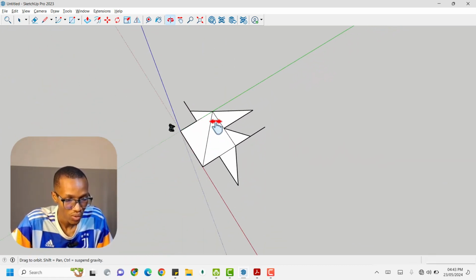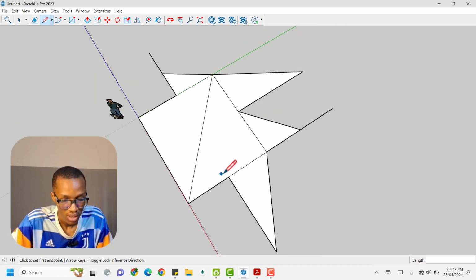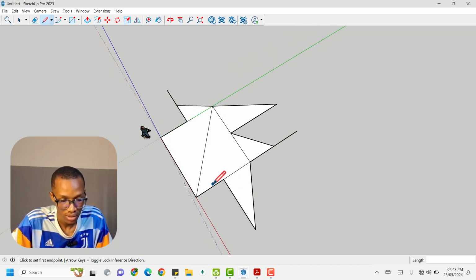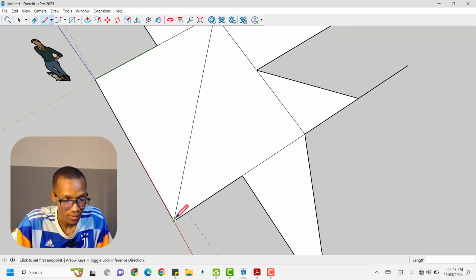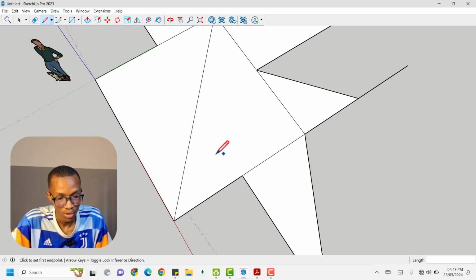All right. So one of the things you need to know is, because we have started dealing with the drawing tools, I would want to introduce you to this lower right bar right here. This lower right bar is our parameters. That's where we see the information concerning what we are doing. Now you must have noticed, if you were attentive, when I click and drag, it's showing us the length. It shows you different things based on the tool you're using, but you always want to keep an eye there, because that's what makes for accuracy in your drawing. That's where the CAD comes into play.